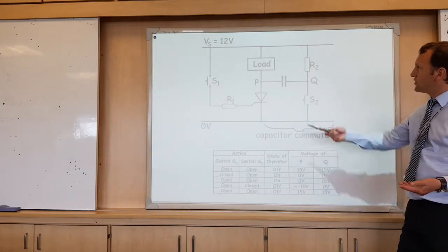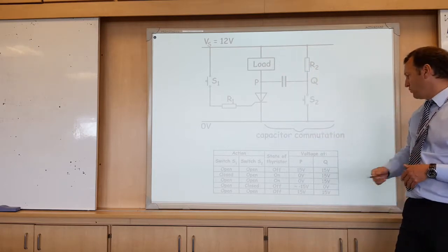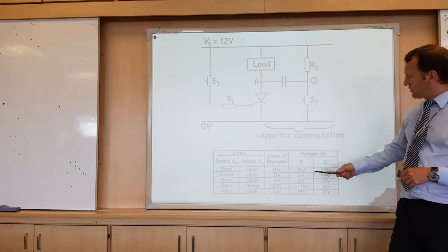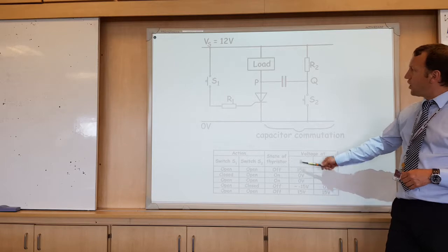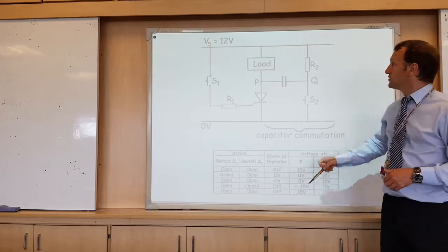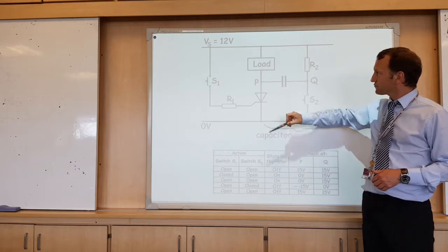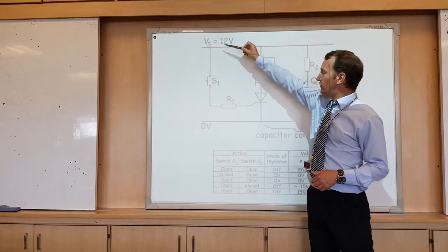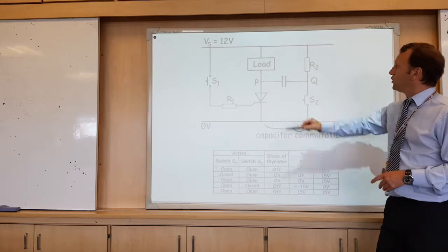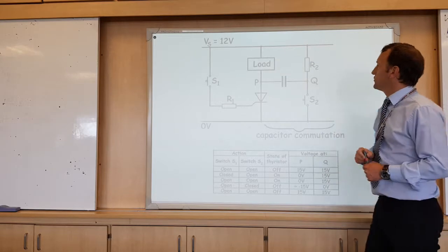So at first when you switch on the circuit, the load, the heater or the lamp, whatever, would be off, so the thyristor is off. One thing that confuses people somewhat is when it's off, it's got 15 volts, or in this case it should be 12. But the full power supply voltage should be across the thyristor. That should really say 15 volts to match these. So therefore when it's off, all the voltage is across the thyristor, none of it is across the load, no current flows through the load.